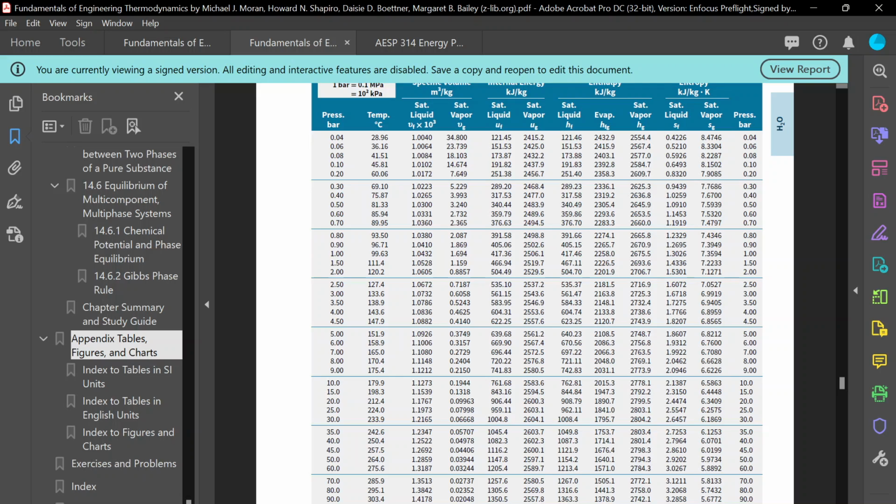H1 equals to, so you are saying that the W dot of the turbine is equal to the W dot of the pump. Who said this? Oh, is it you? But if they are equal, then there is no net work output, right? They shouldn't be equal.